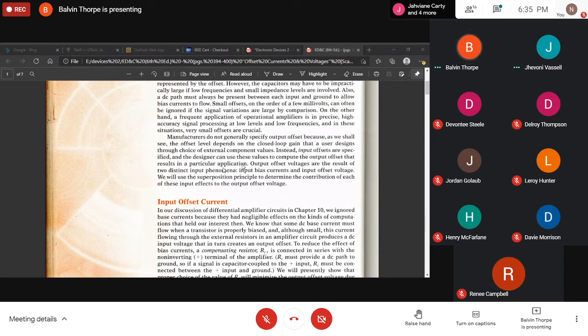In other words, these are the things that they can do at the input in order to negate what you're going to get at the output when there's no input signal applied. But as to what you're going to get at the output, we cannot tell you. That depends on your application. So the manufacturer specification sheet will tell you some generic properties, to include the input offset condition.